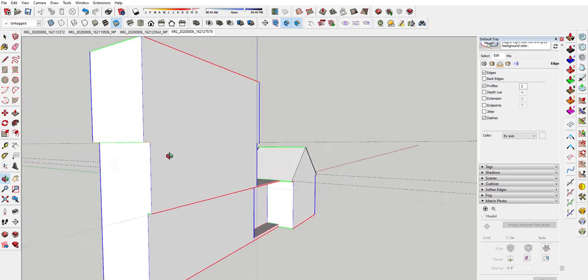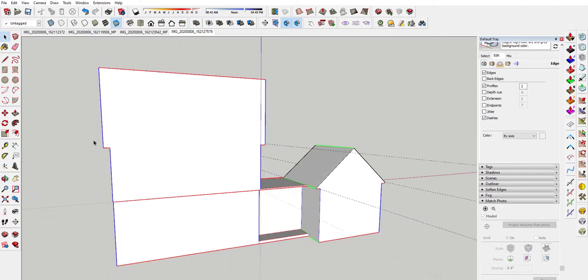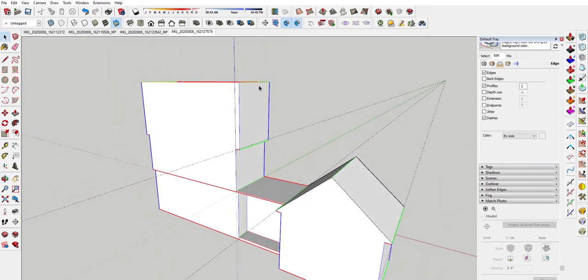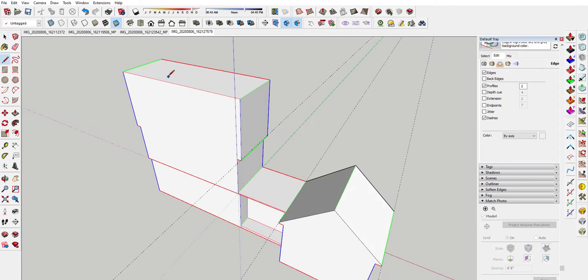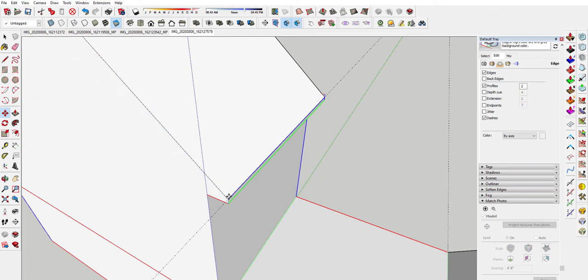Undo is your friend. Now that I've got that where I need to, now I'll tape measure. Well, I don't even need to tape measure up 2 inches because it's lined up with this. I'm going to use this line as my guide. Do a line here to here. Select one end. Hold the control key. Select the other end. Let go of the control key. The move tool. I'll type in M for move. Up arrow key to lock it in the blue axis.